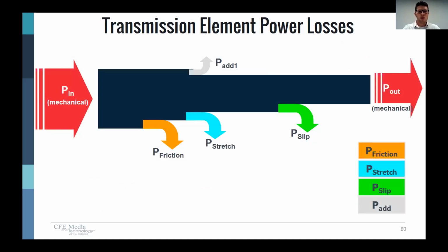We have one more piece to the puzzle, and that's the mechanical component. After the gearbox, it's attached to a transmission element. There's a couple of different things you can have. You can have a belt, a tooth belt, a chain, or you can be directly coupled with a shrink disc or a tapered bushing shrink disc style mounting.